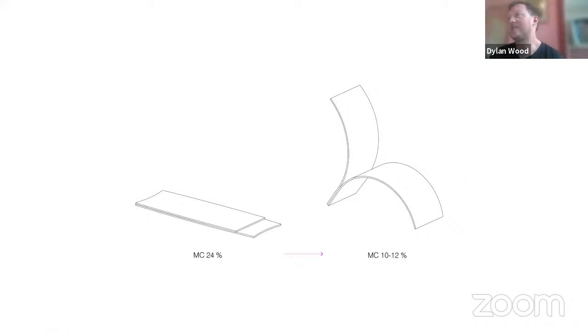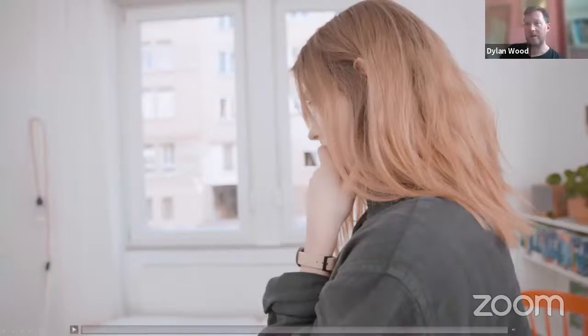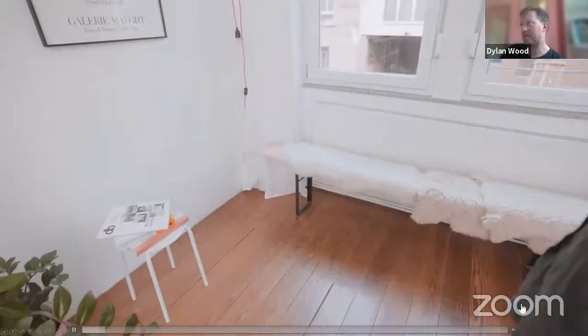So the basis of this study was to look at how we might be able to use self-shaping in wood in order to replace both of those types of issues in the manufacturing of three-dimensional furniture components. So the idea is quite simple, that we produce the parts flat in the factory, but with specific combinations and arrangement of the wood, so that once it arrives in your house and you open up the package, it will slowly shape into its final geometry. So we can quickly watch this to explain.